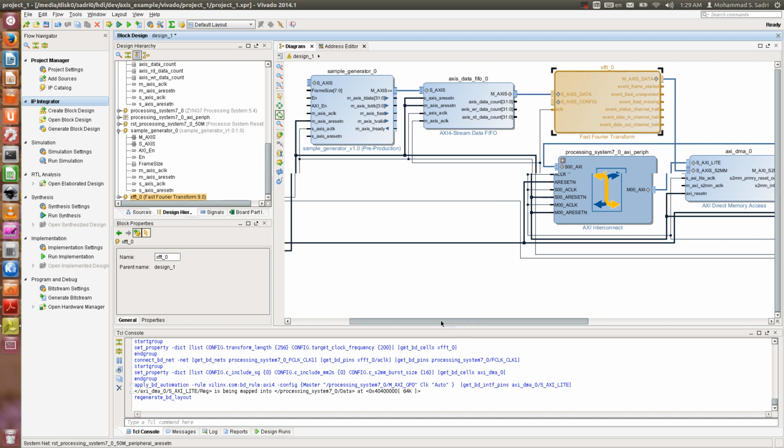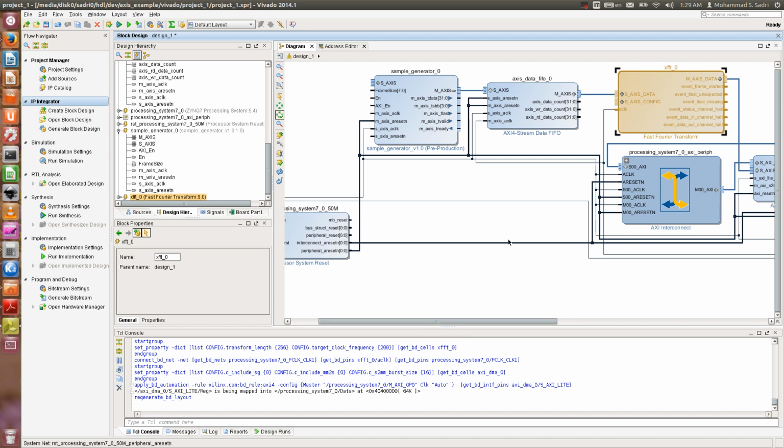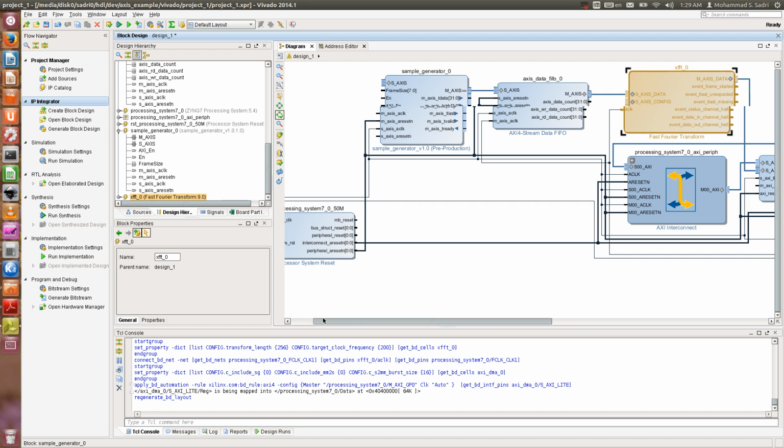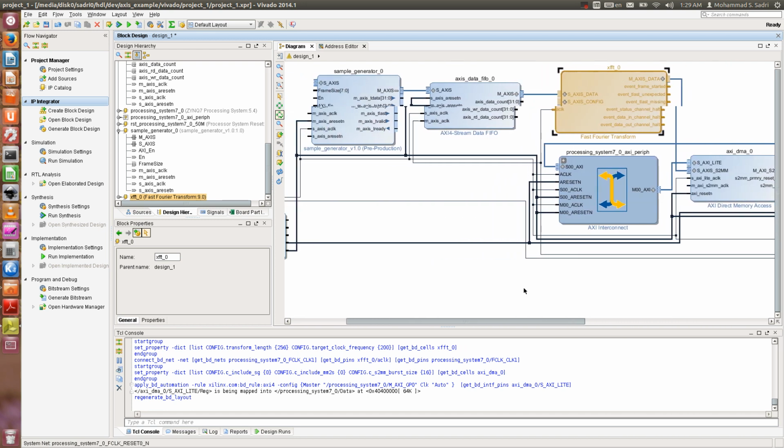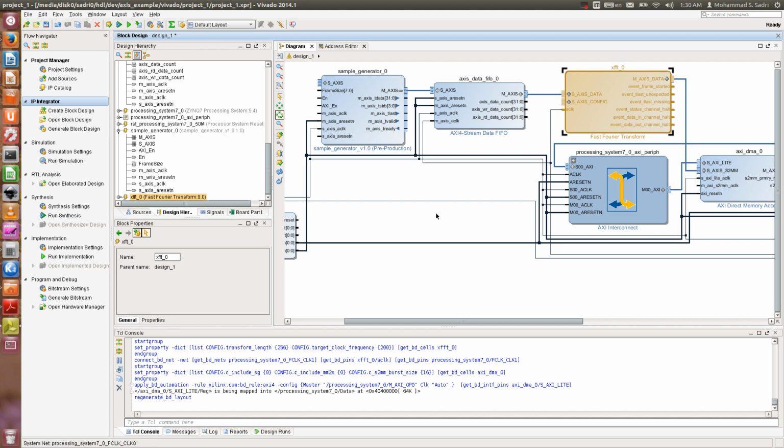So in the next section of the video, I update the hardware, I remove all of these blocks, I just keep these three and remove all of the rest, and for this block I create a test bench and we together perform the simulation on the logic, and make sure that the waveforms are correct and this module is operating correctly.